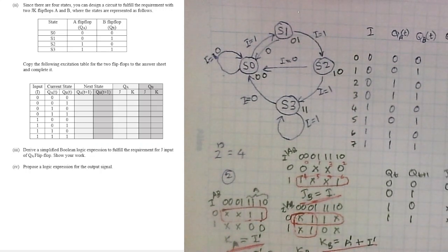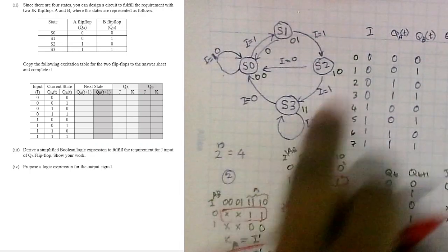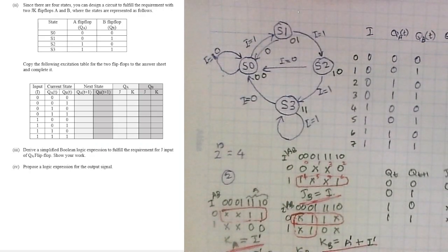I mean, circuit has 2 JK flip-flops. If we set the inputs of those J or excitation signals of those 2 JK flip-flops as these values, it will behave as this entire circuit or entire state transition diagram. So you can verify it using Xilinx or VHDL code and implement this in it and see whether it works, right? So I will show you the timing diagram and explain a bit how it actually implemented and work. But before that, there is another part given in the question.